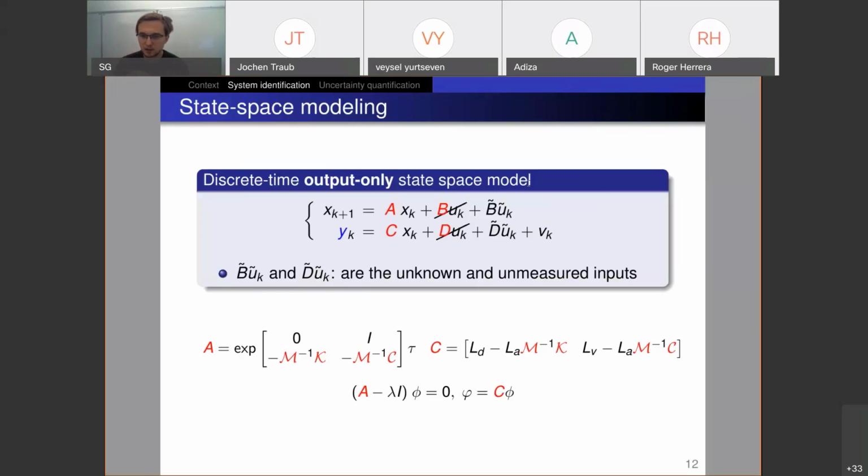So in general, in the literature, the system identification methods are explained by linking the covariances between the output measurements in time to the state and observation matrices, and covariances of the output measurements and the states, also to those matrices.